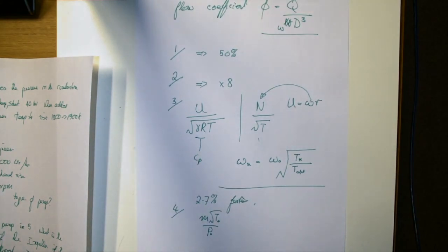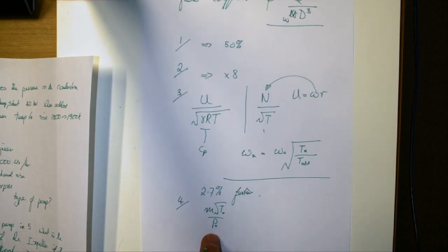That group is a characteristic of the turbine. It's a dimensionless group. It will not change. The turbine will not operate outside that range until the pressure ratio is so negligible that it starts dropping. But provided we're in the sizable pressure ratio range on the machine, this is constant.